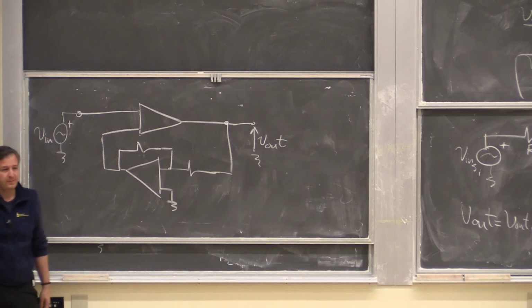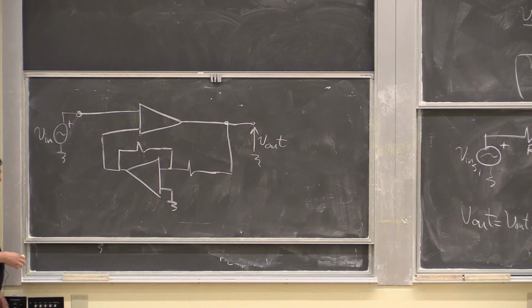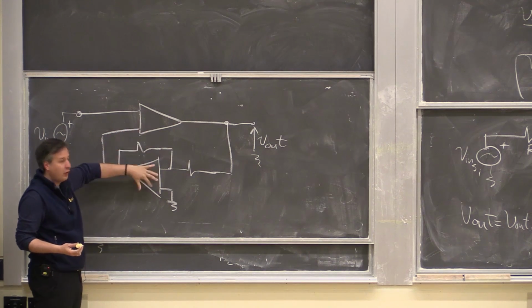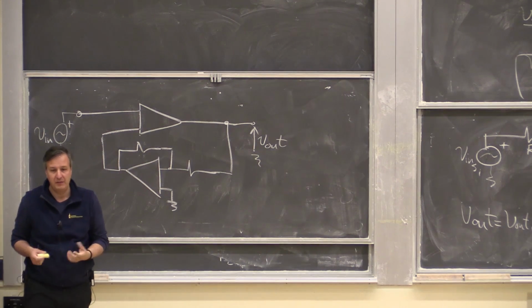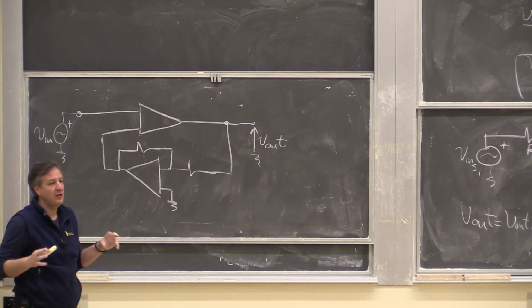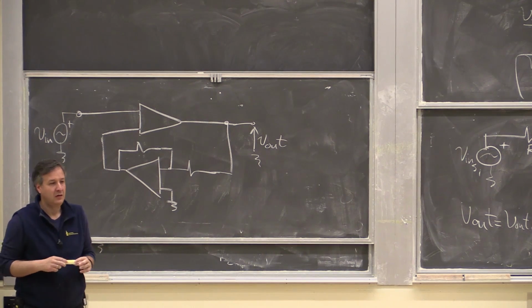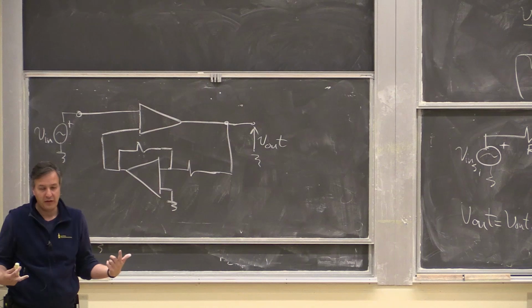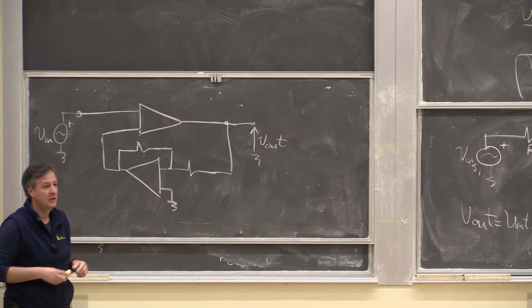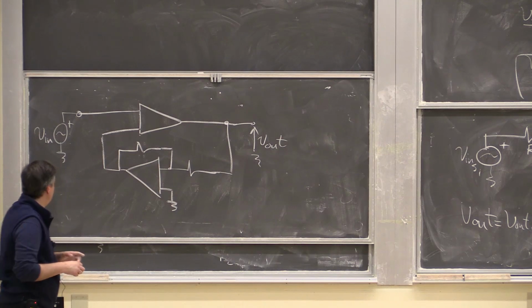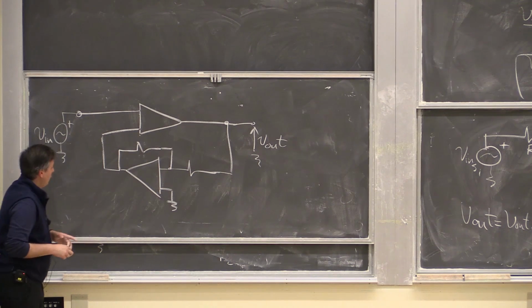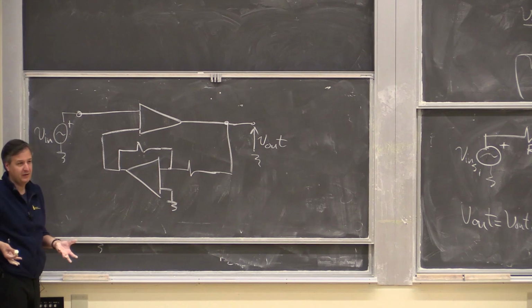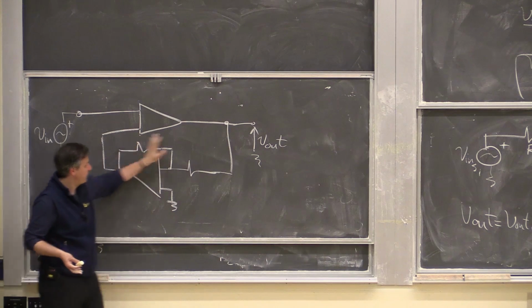Okay, so here's the circuit. One of the things to figure out is the polarity so that both of these things are in negative feedback, right? But what observation can you make by just looking at this? I mean, we can go and solve it through nodal, okay, once we figure out the polarities. But in order to do that, yes? Overall, it seems like it's an inverter. Sure, but it's kind of hard to say without trying to decompose things, right? So what would this block look like?